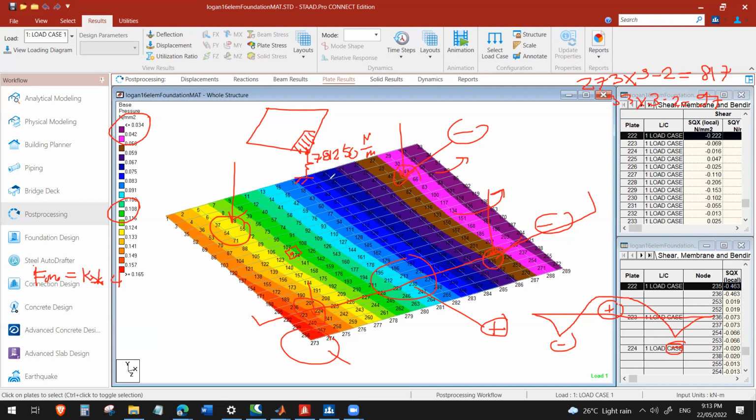So the stiffness 78,250 times 4 is multiplied by the displacements, right? From the basic formula, F is equal to K delta. So to find the force, multiply the stiffness by the displacement. And the displacements are known already; we have already solved that. So the displacement at the corresponding node, vertical DOF. That's just a force.